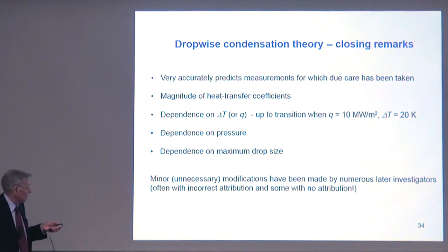Closing remarks on the theory. It very accurately predicts measurements for which due care has been taken. It predicts the magnitude. It predicts the dependence on delta T or Q, all the way up to 10 megawatts per square meter. It predicts the dependence on pressure. It predicts the dependence on maximum drop size.